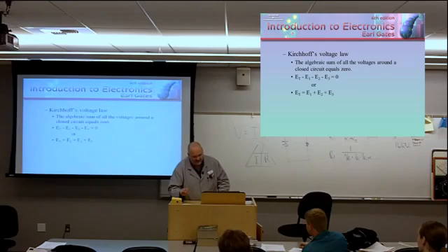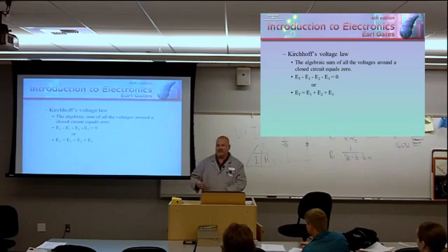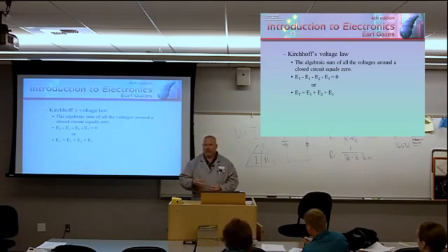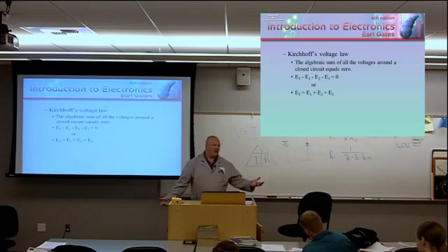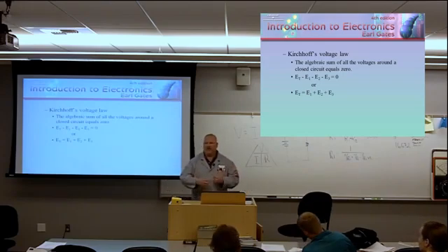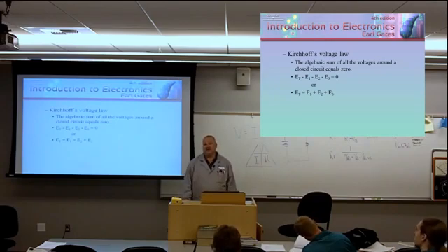It's not. The most complex electronic systems could be rapidly troubleshot, keeping these fundamental skill sets in mind: Ohm's law, Kirchhoff's law, the 5 basic parts of a circuit. Is my source good? Is my load good? Is it the interconnects? Can I prove that? The other thing you've got to do as a technician is pay attention to what you can check quickly. What can you check quickly?